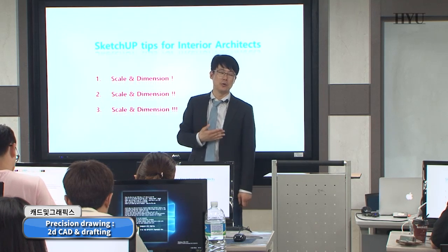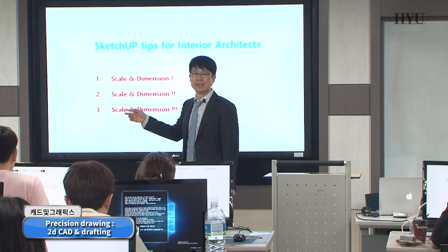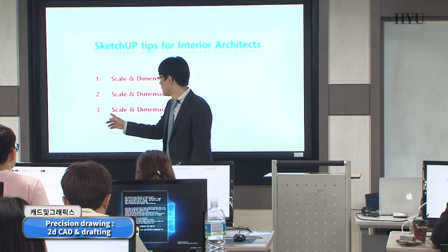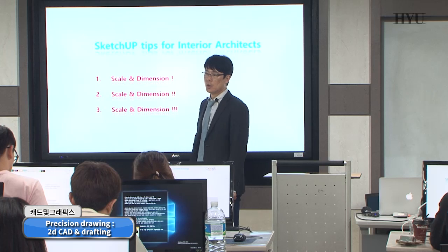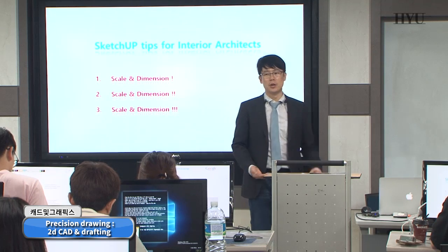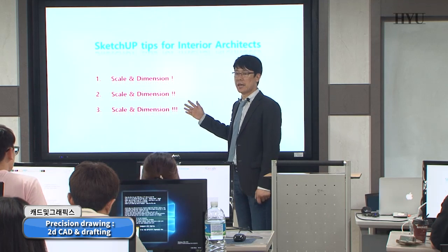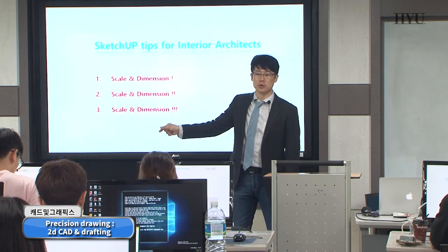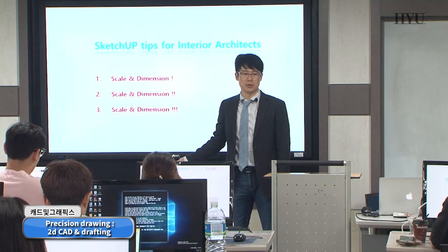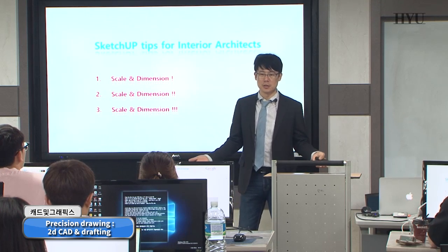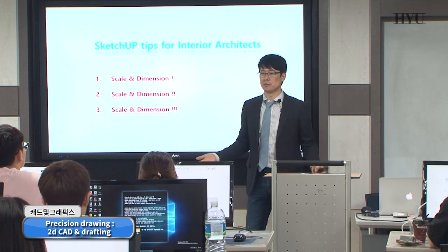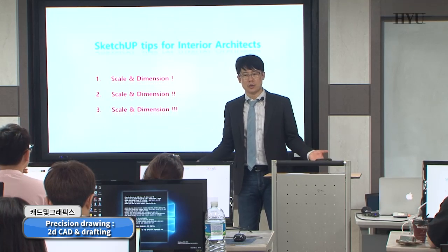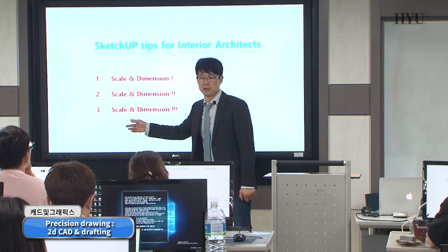For architecture, for being an architect, for interior architecture design, you have to take care of the concept of scale and dimension. Even if I say it again and again, you usually skip this very critical aspect of design. For example, you usually create window frame borders of 50 centimeters, 500 millimeters. You usually create walls of 1 meter thickness, columns of 2 meter radius, or sometimes just a 10 centimeter radius of columns. There are no such things in terms of human scale, okay?